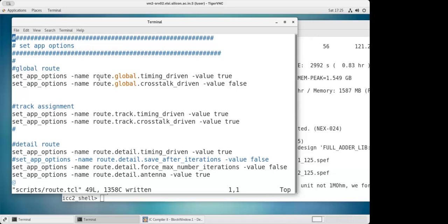global route. Now once the global route is there, you have chosen the path. Then in that particular path, there are different lanes. Now you say, if you stick to this particular lane, there is no problem. Everything is clean. It's more organized, not like in India where people are just shifting lanes like this. It's like in the US: if you are in this particular lane, you have to stay in this lane. That is something known as track assignment. They will assign the track to you. Once you are on this particular highway, you have to stick to this particular track, this particular lane.